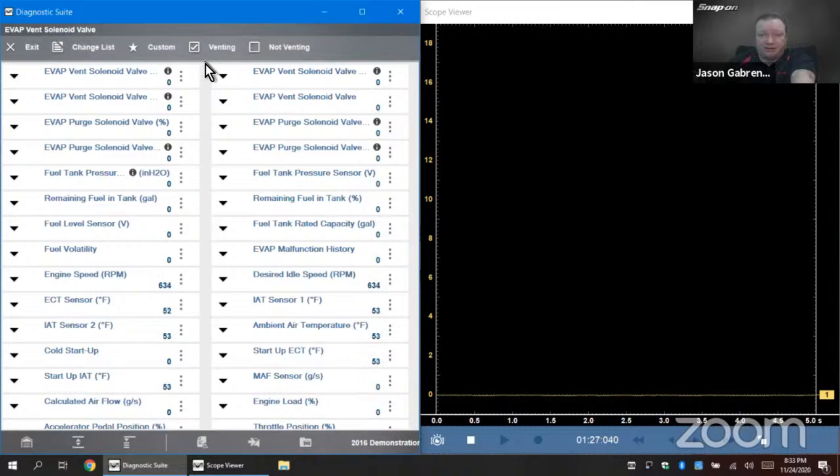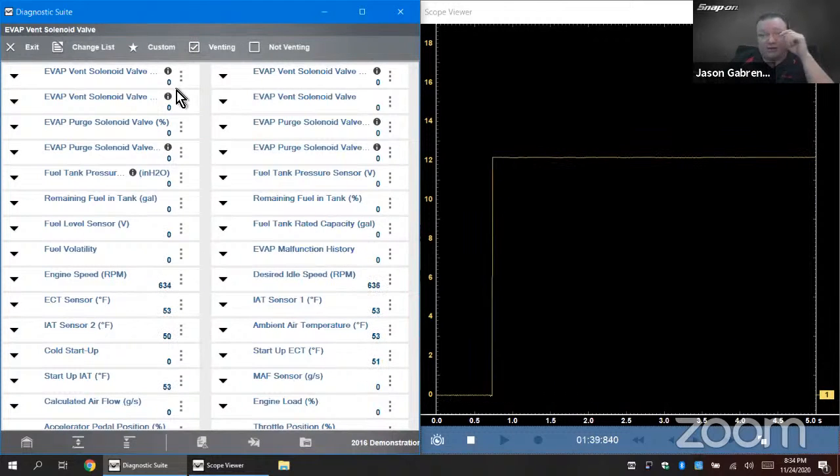So the next thing I would do on my control side is it's not changing. So is the voltage making it through the solenoid? So I'll unplug from that side, plug it into the other side, and see if I get voltage. So let's say in this case, I hooked up to the other side of the solenoid, the supply side that goes to the fuse box, and I see 12 volts.